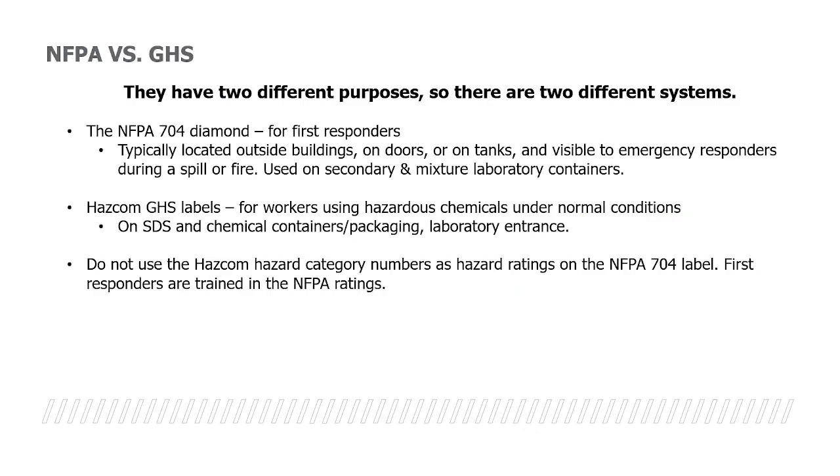What's the difference between the NFPA and the Global Harmonization System? What are some of the big differences? I did hit on these a little bit earlier. The NFPA diamond is going to be for your first responders. It's typically located outside of the buildings on doors, or it may be on tanks. It also is visible to emergency responders during a spill or even a fire. It's used on secondary and also mixture laboratory containers. You will find the NFPA diamond located there.